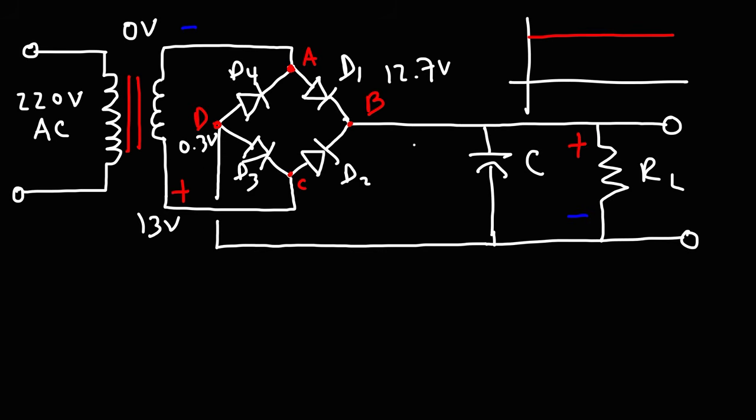So while it's charging, a lot of current will be flowing through this capacitor. Now keep in mind, there's no current that actually flows in between the dielectric of the capacitor, because there's an insulating material there, but the capacitor is charging. Electrons are being pumped from one side of the capacitor to the other side, and so you have a large current flowing through these wires here for a short period of time.